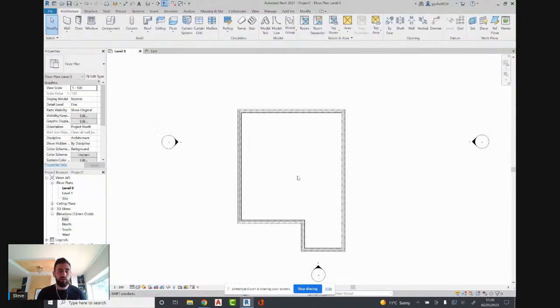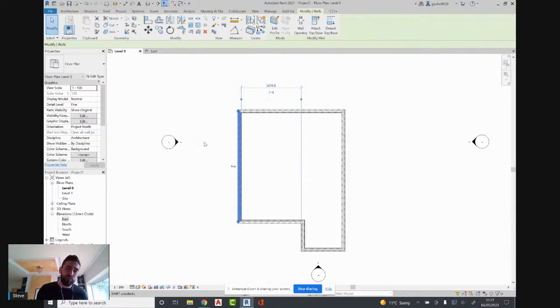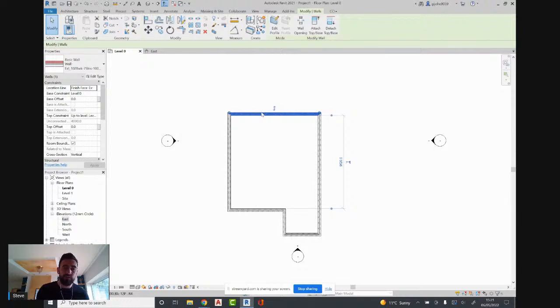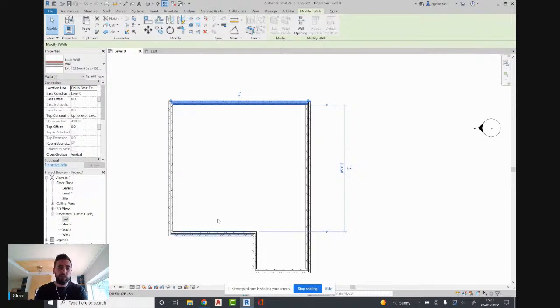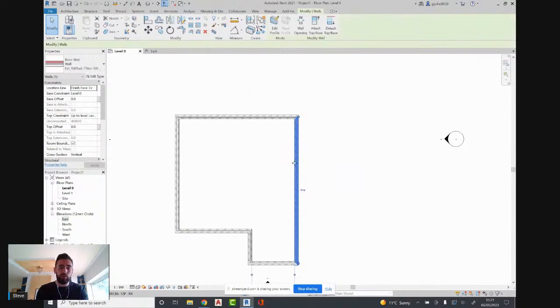And we can now use the revise it method, which there is an unconfirmed rumor that Revit actually means revise it. So it means that we'll place in our components and then afterwards we revise that information. So this wall here, I want that to be 8,500 mil. So I select the upper line, and there's my dimension. I change it to 8,500 and I've repositioned that wall.